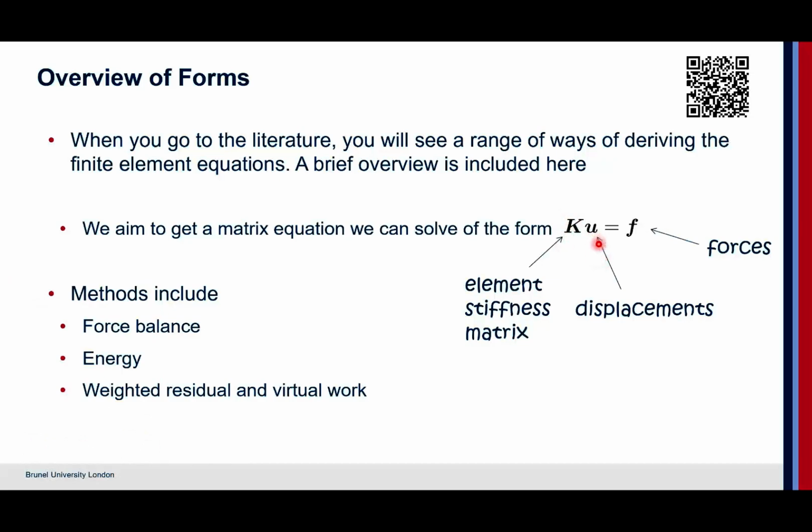U are the displacements. In that case we've just seen there were temperatures, but as we said they could be considered as the shear in a solid substance or the shear in a fluid, deformation of the material. So they're generally called displacements because finite element analysis is more often used for solid mechanics and was derived from solid mechanics. And then this right hand side, these force terms, in our case have been 0.